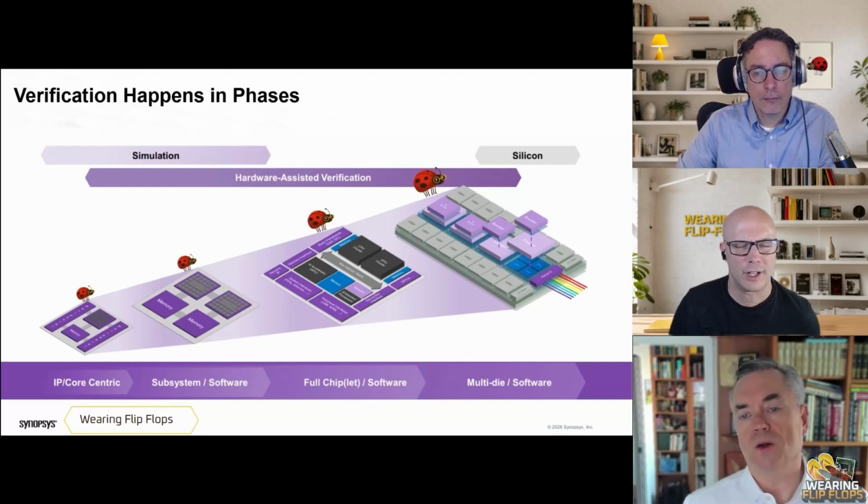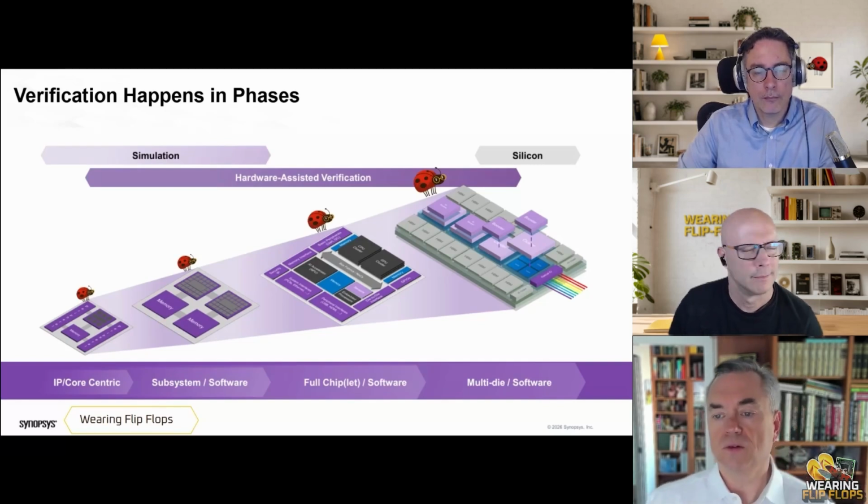You mentioned multi-die. What's that? Multi-die chiplets. We are approaching the reticle limit in design size, the physical limit of how much silicon you can actually manufacture with the right yields, but also we are approaching a phase where it's not always the most aggressive technology node that gives you the best results.